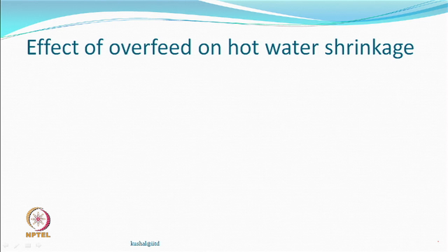So, let us assume that in hot water at the temperature that we are talking about, we expect some shrinkage to take place, because it is, let us say, a thermoplastic yarn. If it is not a thermoplastic yarn, the temperature may not affect, but the water may affect. So, let us say if we look at just the shrinkage, because we said either it is because of relaxation in the molecules or because of swelling.